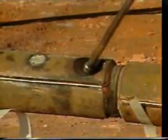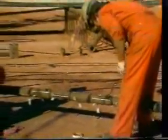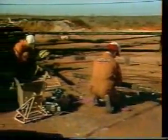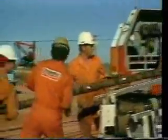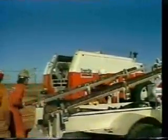A variety of gun designs exists, depending on whether the gun is run into the hole on an electric conductor line or on the end of the tubing, whether the gun is to be fired through the casing or through the tubing, whether the gun is retrievable or expendable, and the size of perforations desired.